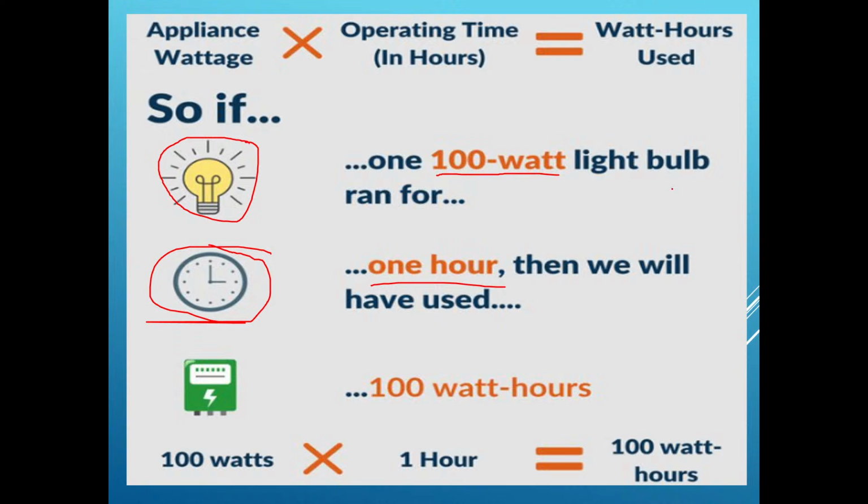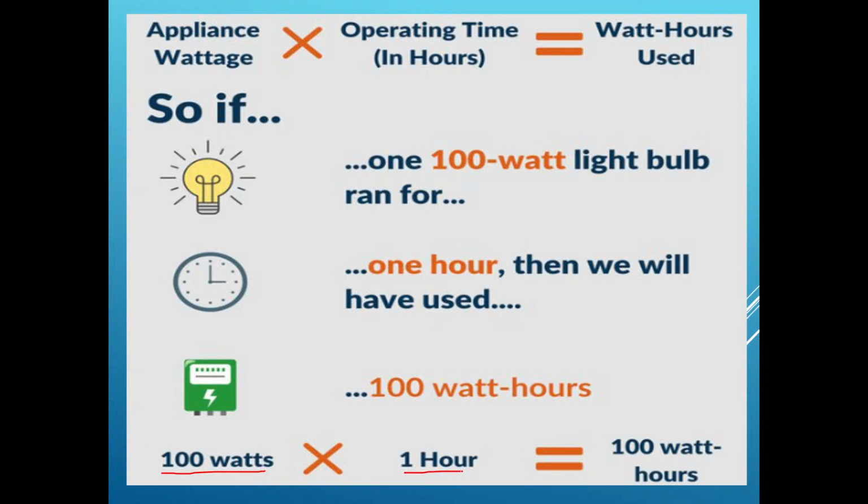Now, how much energy is consumed here? Wattage into operational hours. So 100 watts into 1 hour will give us 100 watt hour. That is the energy consumption.